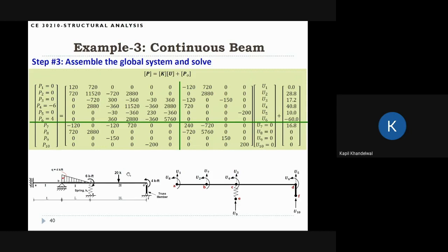Okay. Again, remember that the load of 20 is actually a member force. So it creates a fixed end moment. You don't have to worry. We are not taking 20 into account as a nodal force, because it does not act at any degree of freedom. This acts within the member itself. Similarly, this distributed load Q, like this triangular distributed load, is acting as a member force. It's not acting as a nodal load. And these are the only nodal loads here, from P1 to P6.